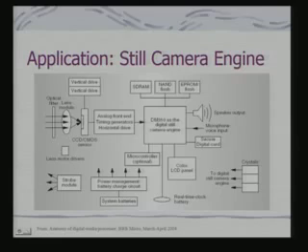So here you have got the CCD sensor, analog front-end, timing generators and horizontal drive, and that gets interfaced through your CCD controller, which is sitting on the chip itself. You can have an additional microcontroller, which may be optional. You have a power management circuit. These are basically your memory. Okay, these flash are where the programs should be stored. You have got a speaker output, microphone voice input, secure digital card. You can also ensure a kind of secured access, and a color LCD panel, which would be the interface to see what is the image being captured.